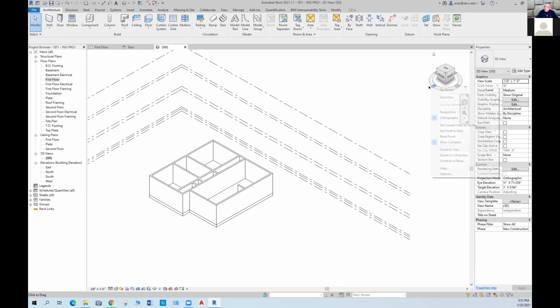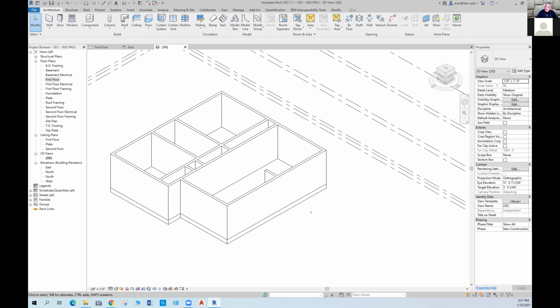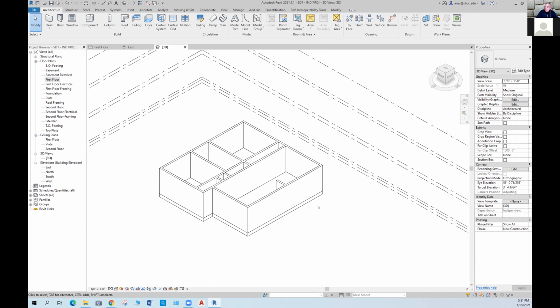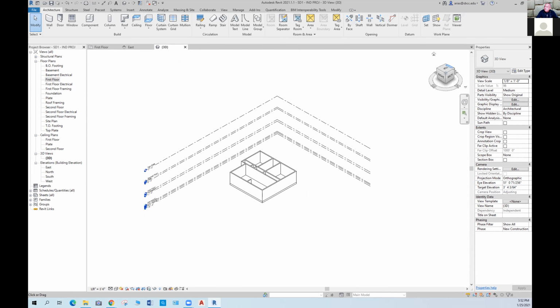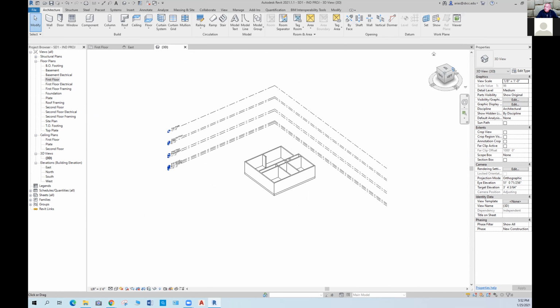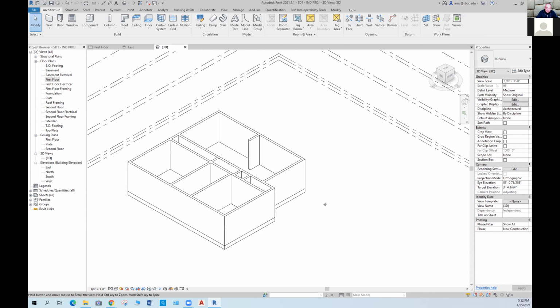Although the view cube could have a perspective view, I don't want to do that because in a perspective, the views are not true views. So for me, that's a non-starter right now. So I can do that. Go to the corners of the view cube, and in that way you move around the model. There are other ways to do it, but this seems to be the best.